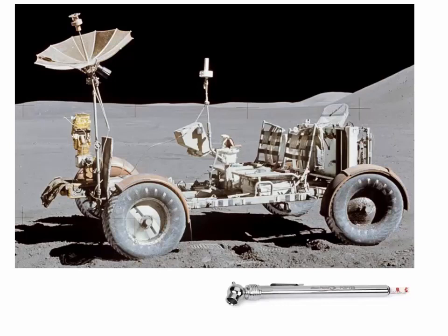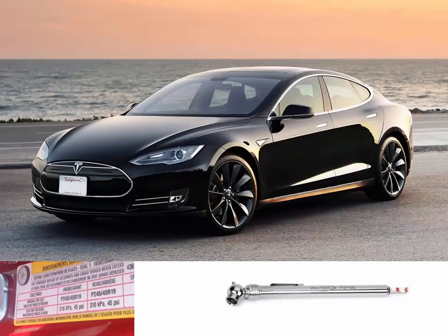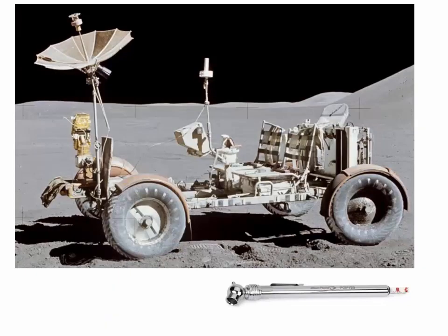And so, in the case of the Tesla on Earth, you're measuring that tire pressure relative to the air pressure that's pushing in on the tires. There isn't any surrounding air pressure pushing in on these moon vehicle tires. And so even if it was the same absolute pressure in both vehicles, the so-called gauge pressure reading would be different on Earth than it would be on the moon.